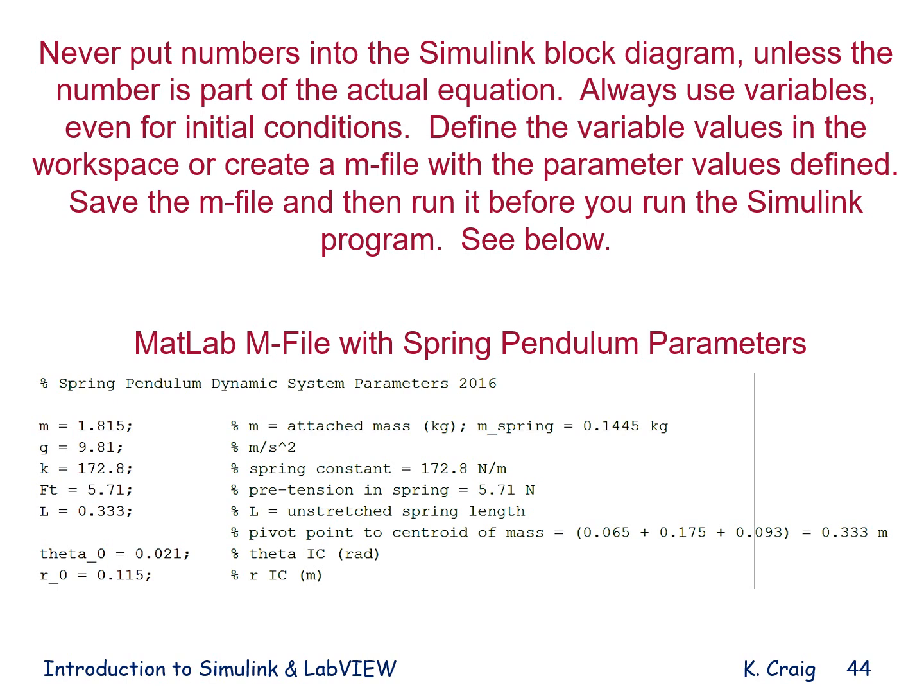But you never want to put the values of the parameters in Simulink. So for example, if the mass M variable appeared in 5 different places in your Simulink block diagram, and you wanted to change it, if you put in the value in your Simulink diagram, you would have to change it in 5 different places.